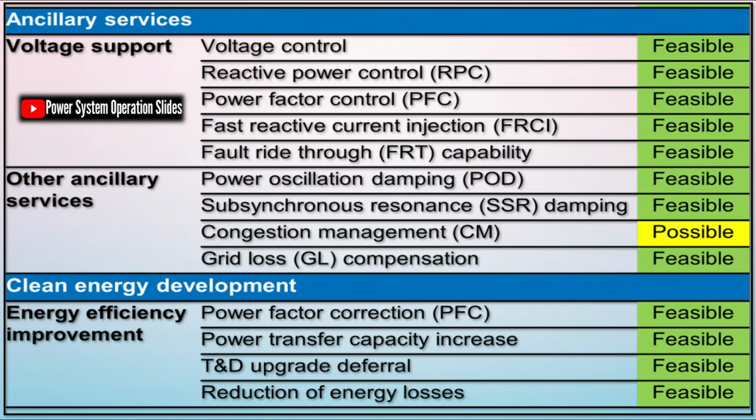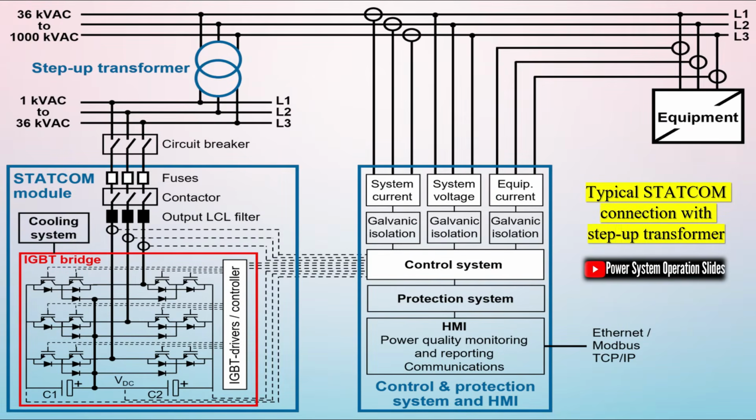At low wind speeds, turbines may not generate enough reactive power to support grid voltage, leading to under-voltage conditions. In these scenarios, STATCOM or SVC can inject the required reactive power, ensuring voltage compliance even when active power generation is minimal. This capability is crucial for maintaining continuous operation and avoiding unnecessary curtailment.